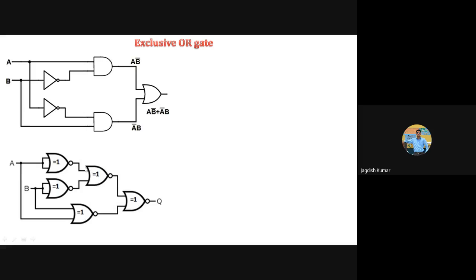And then this is being fed to a NOR gate. Now you will say, okay, we are not using AND gate here. But then you will see that this NOR gate with NOT gates at input will be equivalent to AND gates. We will be doing this in the Boolean algebra part. There are certain theorems which we will be using and proving as well, so that we can establish the equivalence of these two circuits. If you are not convinced, you can try that simple hit and trial table, truth table actually.